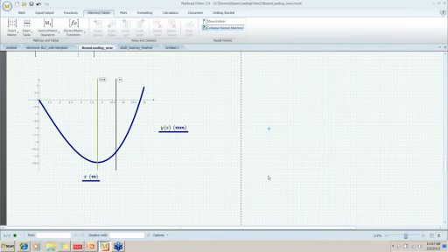And then I have another one. How effectively can existing Mathcad 14 worksheets be pulled forward into Prime 2.0? Okay, that's a good one. There's a built-in converter in Prime 2.0 that will convert your existing files into the Prime 2.0 data format. The Prime data format is different from Mathcad 15, 14, and before. It's a totally different format, so you have to run your worksheets through the converter, and the converter is built in.